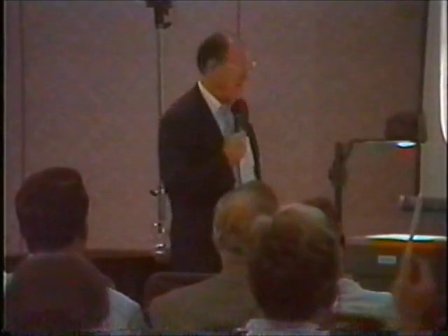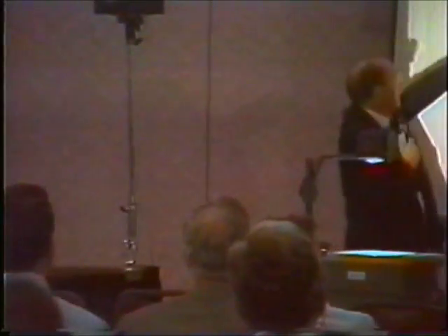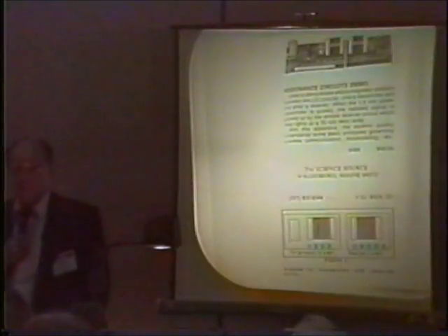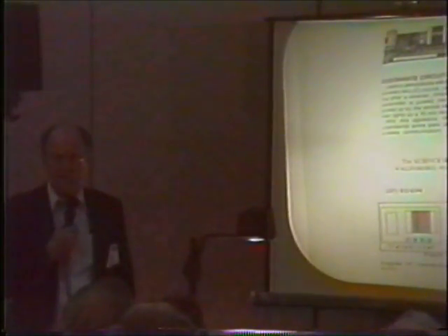Well, there has to be some sort of circuit interrupter, a key or something else that goes with it. Well, there's a capacitor in there. A small capacitor. Well, actually, you can see there's a butterfly capacitor there that's like 250 picofarads, which would get you into the AM radio frequency with that particular coil winding.